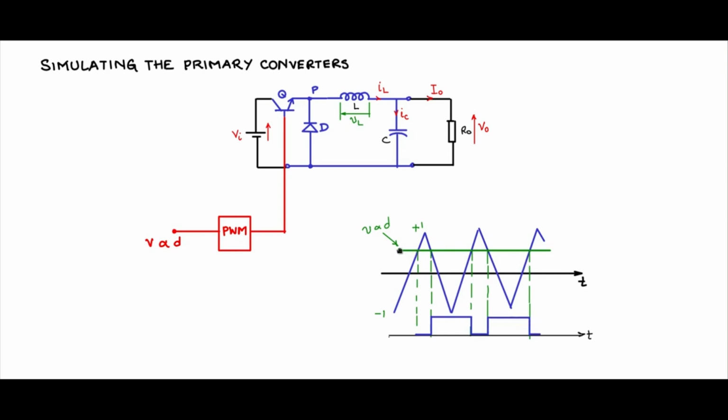So as this control voltage moves up and down, you will see a modulation happening in the pulses, and these are the pulses that will be used as control signals for Q, and this is what you will be seeing at these points. Later on I will discuss in detail what goes into making the PWM, so that you can build other PWM blocks and techniques.